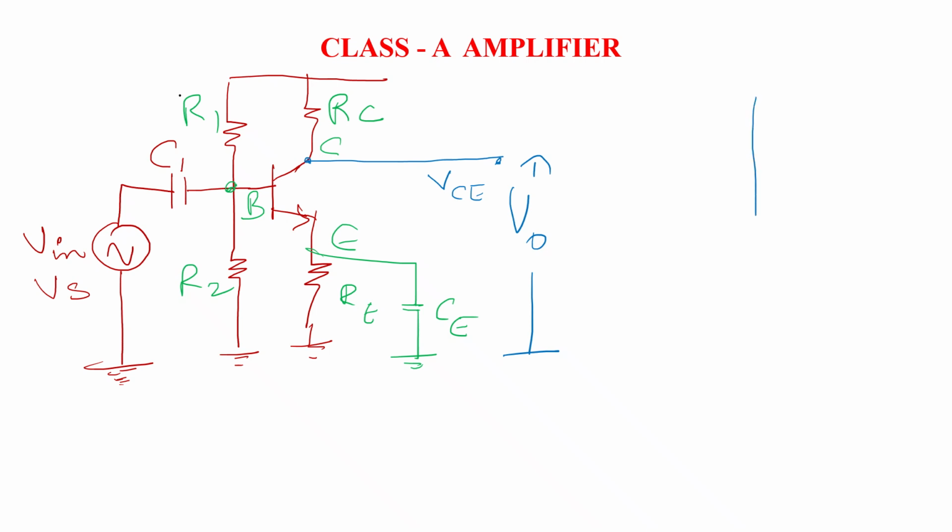That is observed from the output characteristic of the BJT, taking VCE on the x-axis and collector current on the y-axis. We know the DC load line. We have seen this in the DC load line, and at the saturation levels. At the stability point, these points are quiescent points.